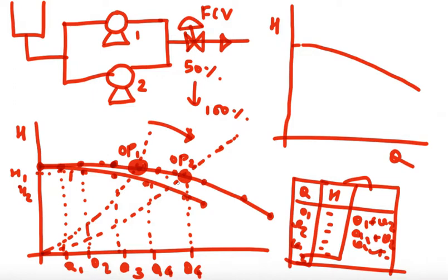But when you are operating the pump toward the right side of the curve, or BP, at that time what will happen? If you see the power curve of a pump, it is like this. Toward the end, this is the power consumption curve of a pump. So when you are operating toward the right, after BP the curve increases exponentially, means slightly increasing at a higher rate.